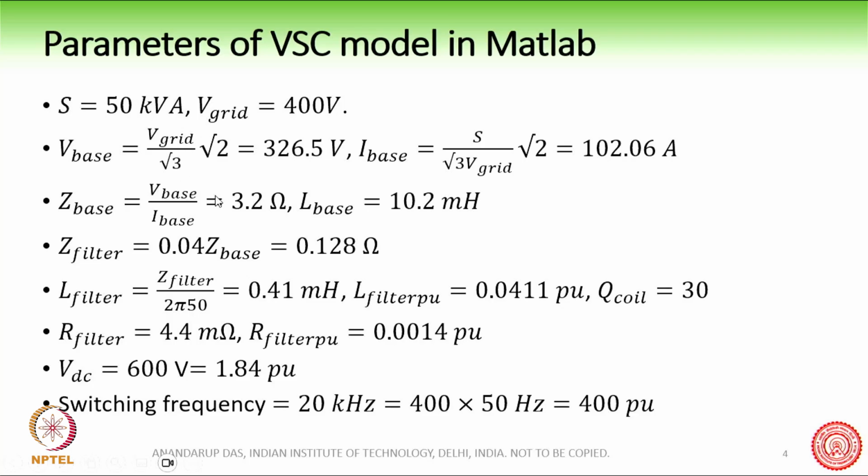We will do the simulation in the per unit system, so we will define these V base, I base, which I have already talked about before, but these are again shown in the slide here.